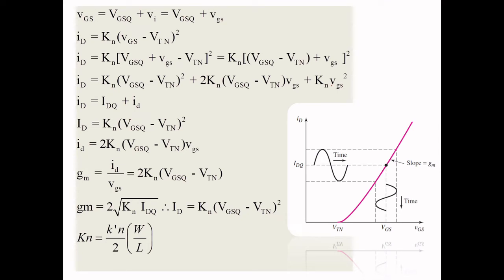The small signal equivalent circuit is a mathematical modeling of your MOSFET. So first your DC circuit should be converted into the AC equivalent circuit. Then in that AC circuit, the MOSFET has to be replaced by your mathematical model. Before that we need to see some small signal parameters. Here you can see the graph. It gives a clear idea about the change of ID versus VGS, that is your transconductance. So the change of ID with respect to VGS is your transconductance, you are aware, right?